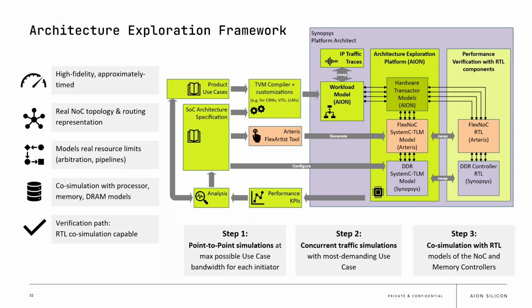And then step three is co-simulation with RTL, where you have real RTL of the NoC and memory controllers to confirm that you meet performance. So that's your performance verification process. Steps one and two are performance modeling. Step three is performance verification.